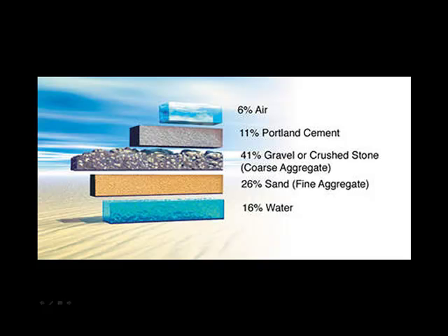It leads to a much more durable product, and it is in fact an essential ingredient. It usually occurs naturally when you mix concrete, but you can also use an additive which will ensure that you get the amount of entrained air that you're looking for.